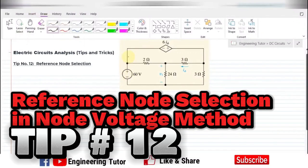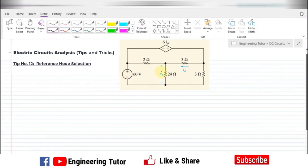Hi all. In this problem we have to find the value of V1 by using the node voltage method. This question also involves a source called a current dependent voltage source. The value of this voltage source depends upon the current I5 which is flowing through this 3 ohm resistor. This is a very interesting problem in which the selection of a reference node can affect the complexity of our problem.